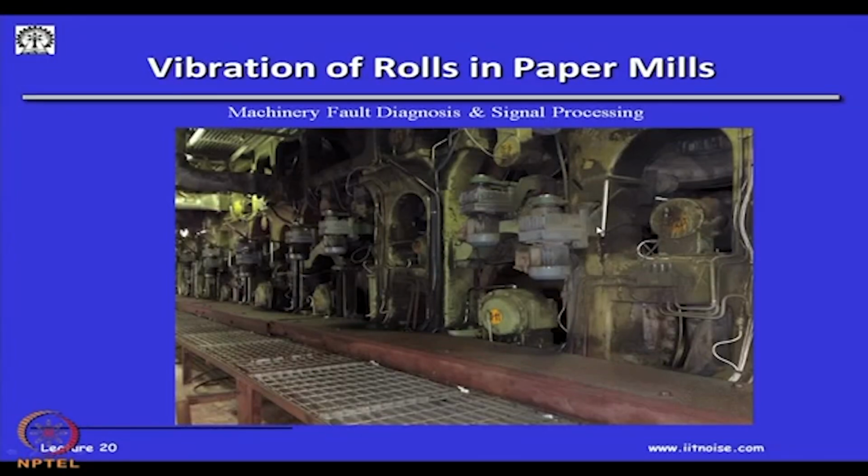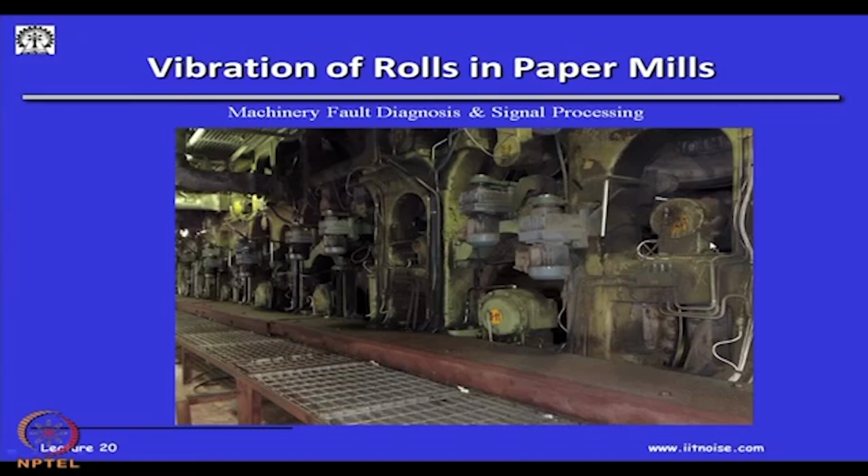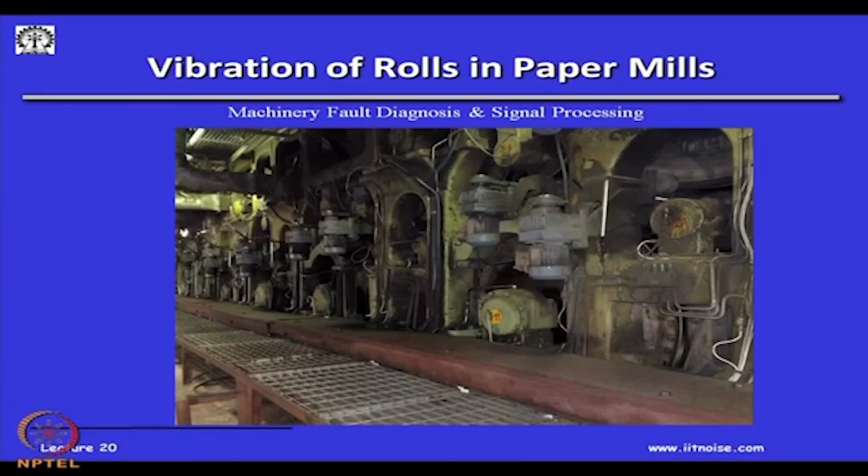Okay, the roll bearings have to be monitored, and they have to be lubricated, they have to be greased. In such a plant, the bearings have to be monitored continuously, and to do that, at every bearing location, if you see the steel cables, steel rope kind of things here, these are actually the cables coming out from the permanently installed vibration sensors at each bearing location. So, if there is a roll number, they know the bearing number.